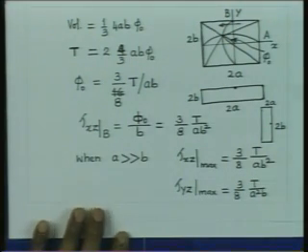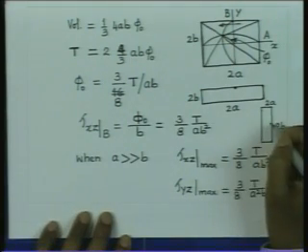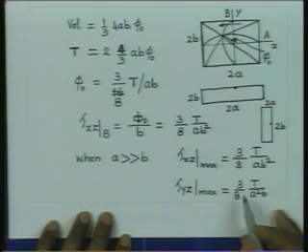I have given you a little while ago that the maximum stress in such a cross section is going to occur here, and its magnitude is 3 by 8 T by A square B.